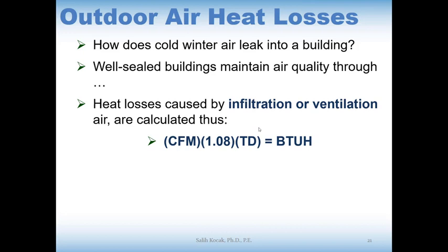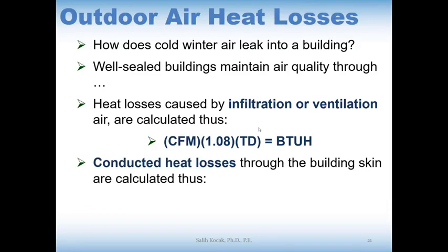We said that whichever is the larger one in terms of CFM, infiltration or ventilation, we are going to be using that one in this equation. And the conducted heat losses happen on the skin of the building, and it's calculated by using this equation.